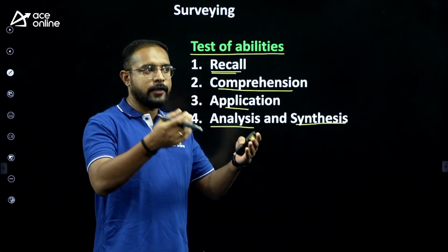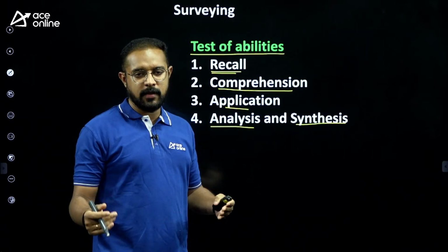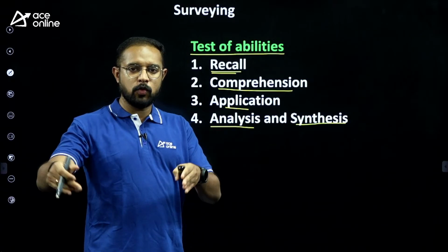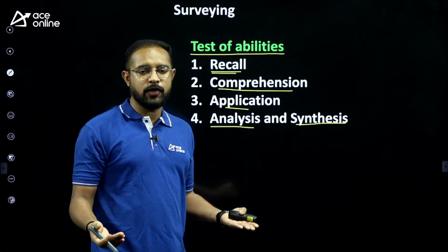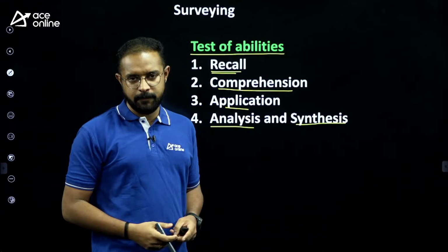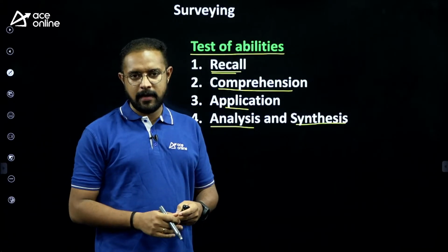For example, a chain is standardized at, let us say, 20 degrees Celsius. If this particular chain is used in a field where the field temperature is 50 degrees Celsius, what is the correct length of the line? So it's very clear that you need to apply that temperature correction.